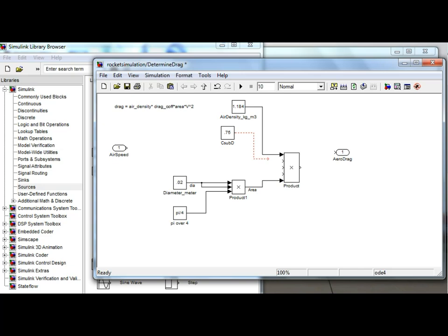And what I did there is, let me undo that. Let me explain one more time. I can drag it a little bit. If I want to route it carefully, I can drag, let go, and I can pick it up, click and drag, and force it to have bends where I want it to have bends, and not where it puts bends all by itself.